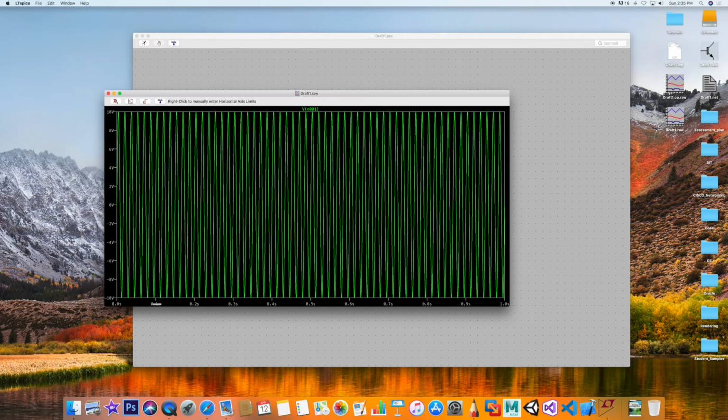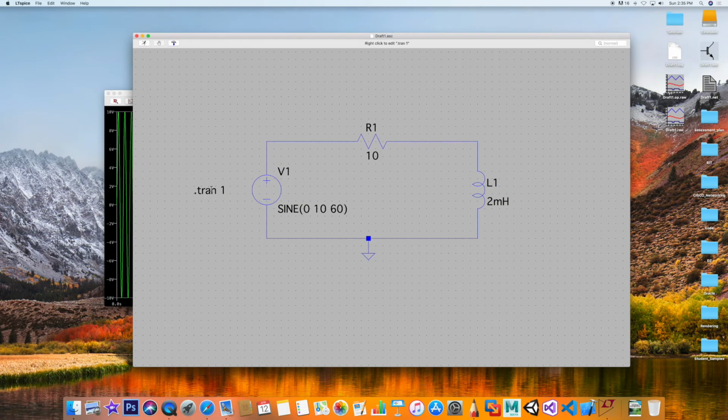And 0.1 probably is where you want to be to see at least 1, 2, 3, 4, 5 cycles, 6 cycles in there. And we can go even further down by 0.05 would be ideal. Well, let's see what 0.5 does and 0.05 will do for us. Okay, so this is a good introduction on how to use this tool. So I can go to the transient here and edit it to 0.1 now instead of 1.